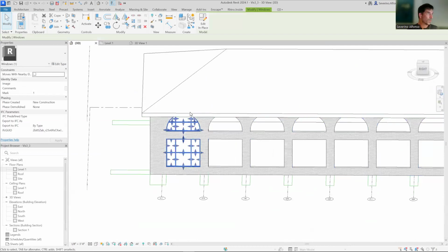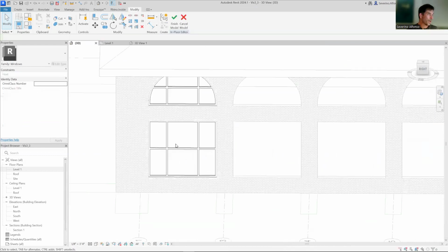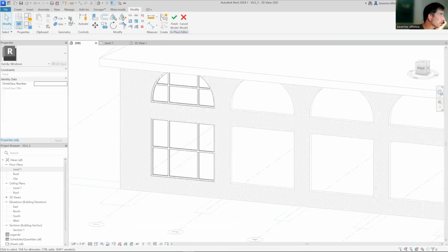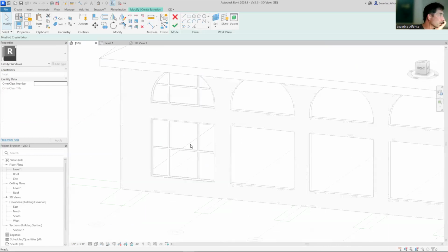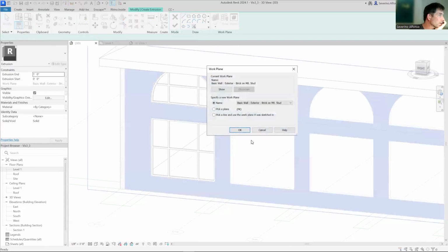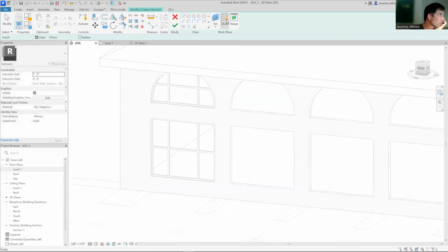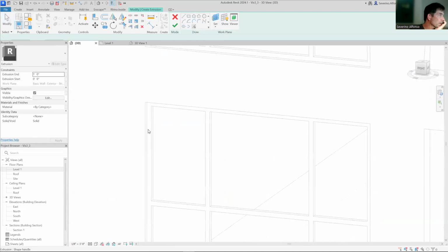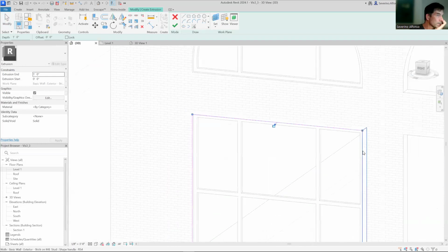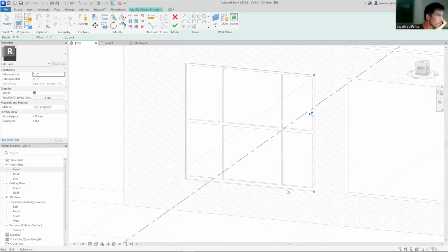Okay, we have one. You could either finish the model and then select that element and copy it around this number of times, but I would probably recommend edit in place and creating also a window pane of this. So the way we will do that is create another extrusion, another pick, making sure we're working on the same wall, which is that one. Show, yes, we are, we're good. And then picking green lines, exterior ones, the ones we started with in the previous project.